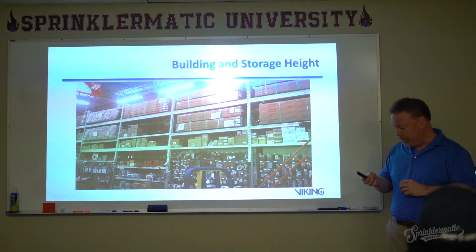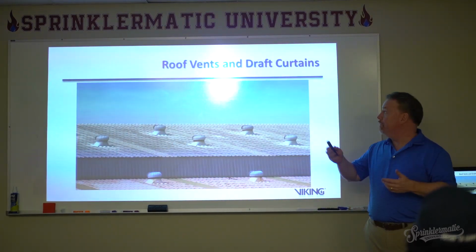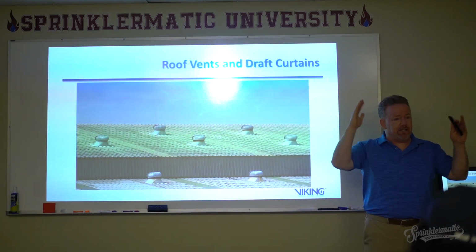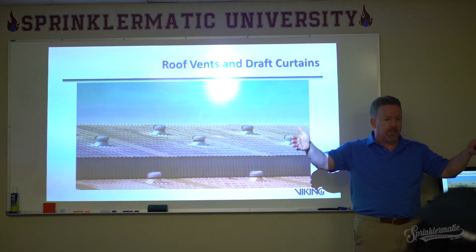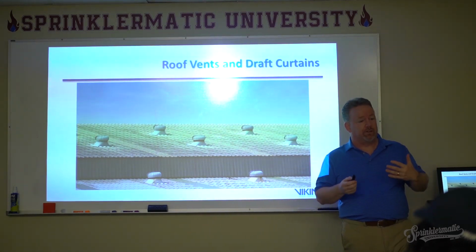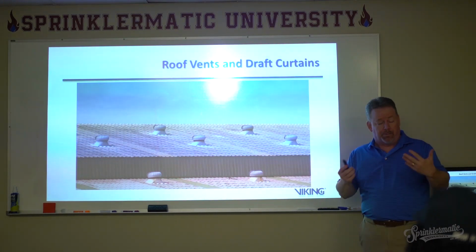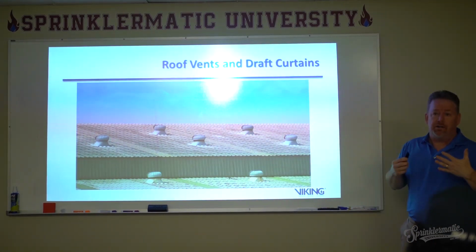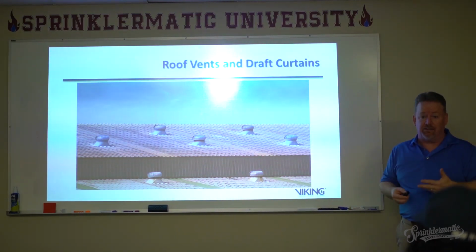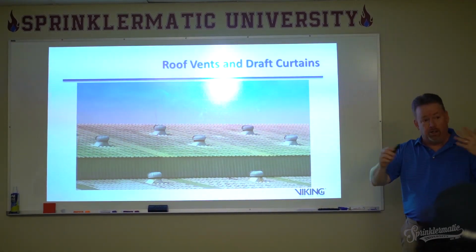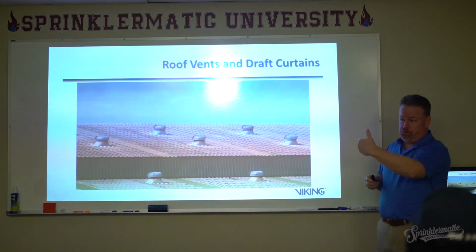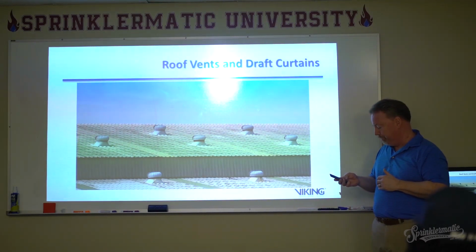Now the same thing goes for draft curtains as well. Draft curtains separating two design areas is fine. Draft curtains within certain areas, especially where ESFR sprinklers are concerned, have a tendency also. Remember, those are a lot of water, a fast response. So what we need to make sure here is that we get the heat into those areas. We don't interrupt the heat flow around the ceiling, because once again, draft curtains could cause skipping of the sprinkler operation.